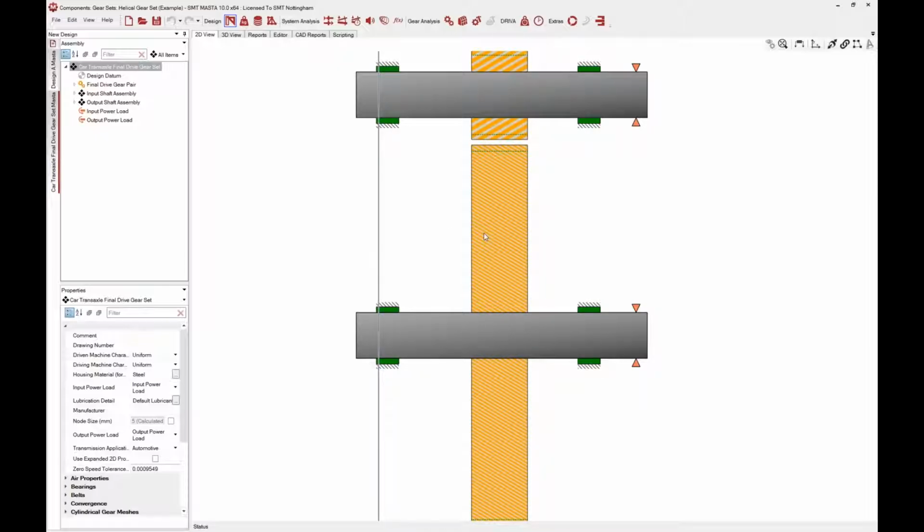As the gear component is directly mounted onto the shaft, it's essentially as if it's manufactured from the same component. If we wanted this to sit on a bond or a spline or a bearing, we could do the whole thing manually by manually creating a bearing component, another shaft component for the blank and connecting them all together. Or we could use the create gear blank assembly option.